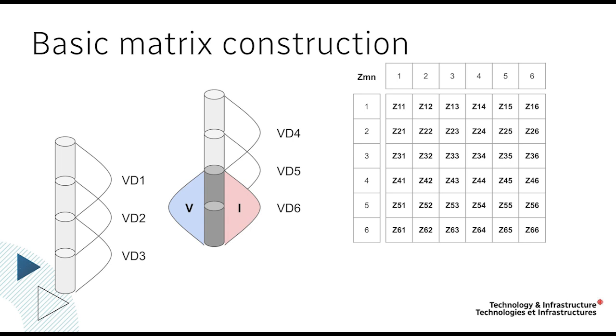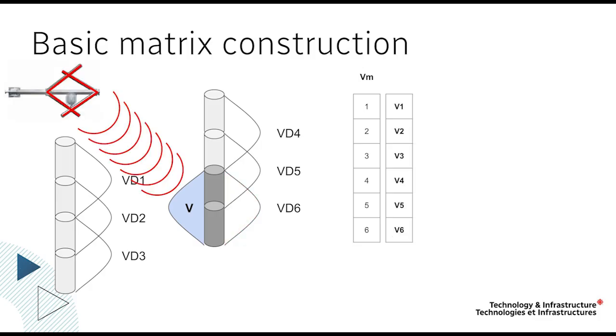All right, so once you've done the whole process, it's really like one simple step repeated n squared times, and that fills your impedance matrix. So that stays there. And then if you have external sources, you can measure the potential that excitation creates on each section to create the excitation matrix, which is a linear matrix that's just in 1n space, compared to the impedance matrix, which is an n squared space.